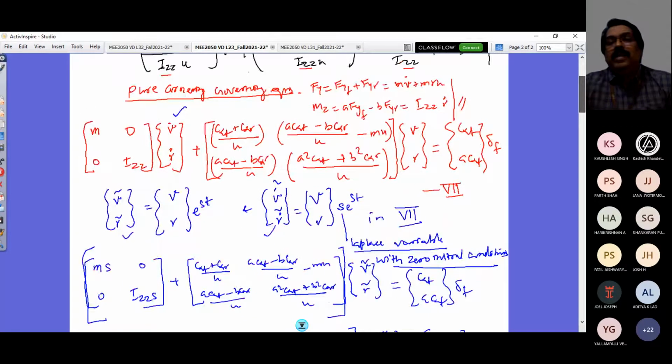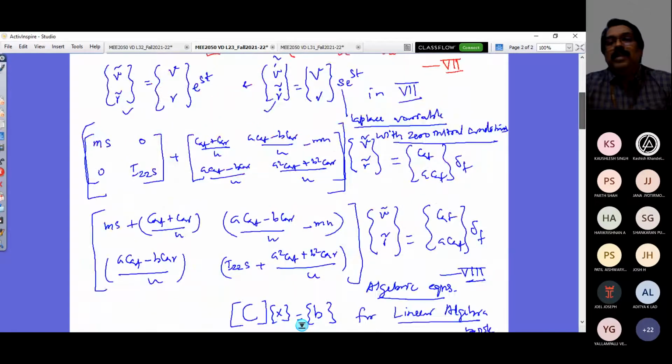On the right hand side, what we have is an input. When you make this input 0 and look at your equation, that is going to be your characteristic polynomial. Or if it is in differential form, it is an ordinary second order homogeneous equation. And that equation is what is to be considered for your eigenvalue analysis, that is going to give you your stability criterion, that will lead to a stability analysis.